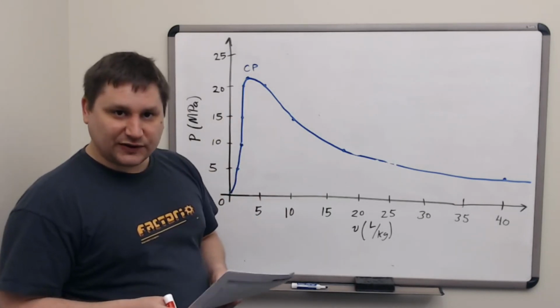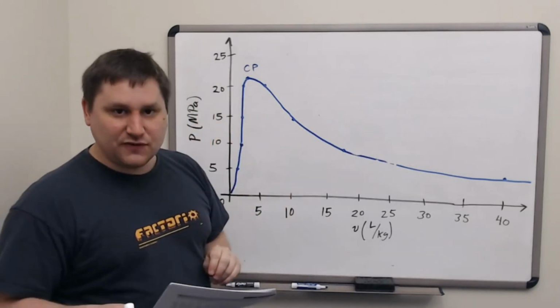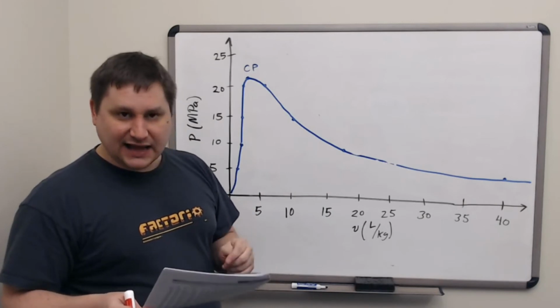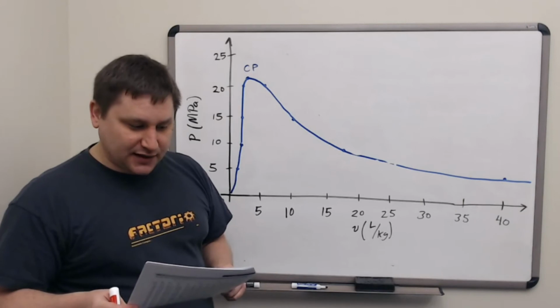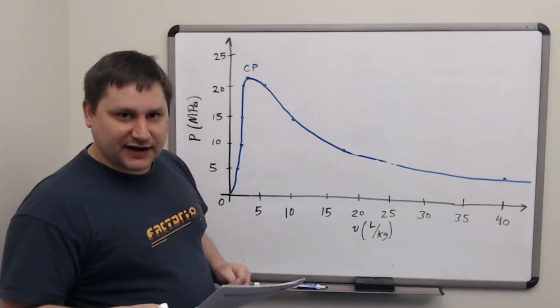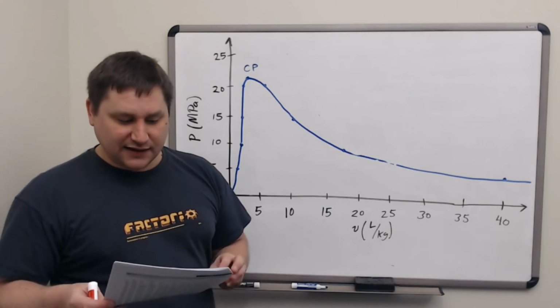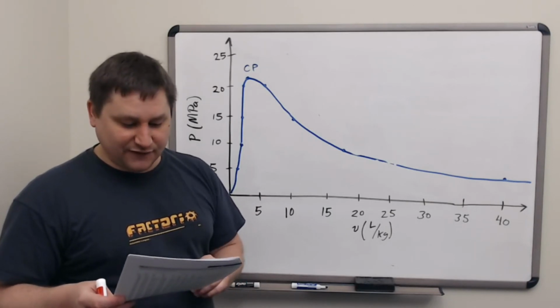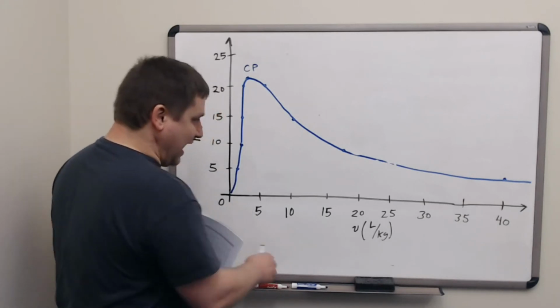If we want to know about the properties of the system when it is in the gas phase, we need to specify two values: the temperature and the pressure, or the temperature and the volume, or the pressure and the volume. This is why table A6 is divided into grids. Each grid square covers a different pressure, and the rows cover different temperatures and volumes. Let's look for a specific location on our graph.